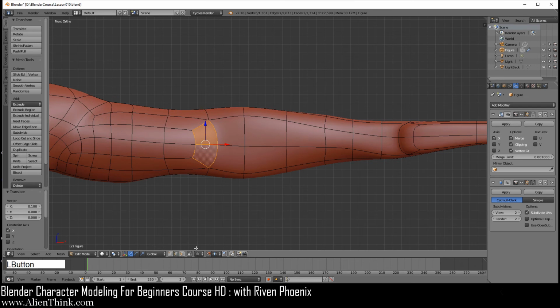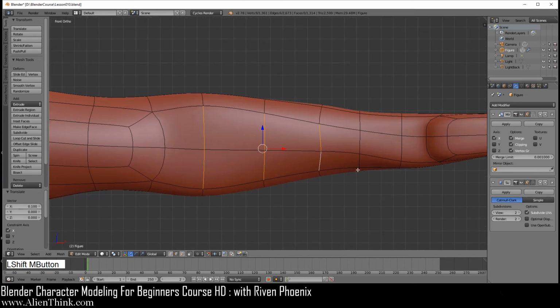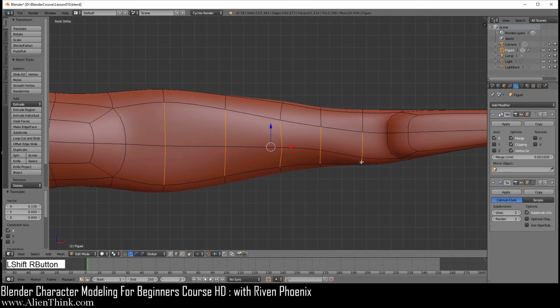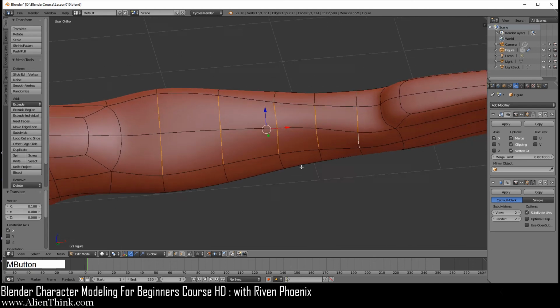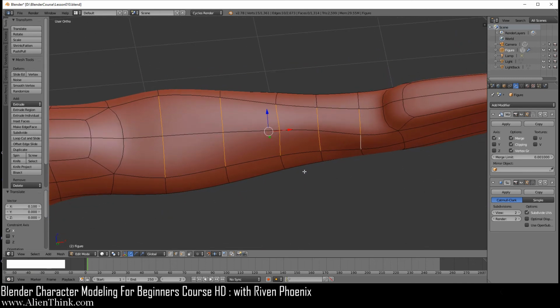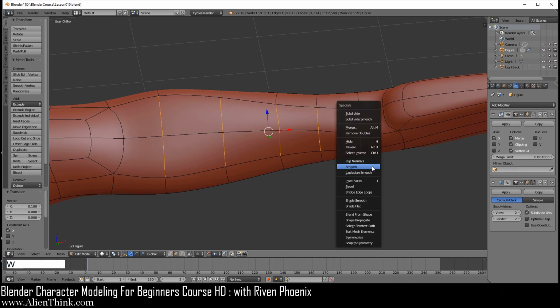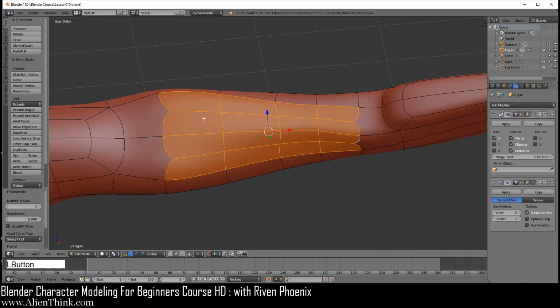Okay, go ahead and select on the edges. Now we can select on this edge, shift key down this one, this. I'm just going to zoom in over here. Select on all these edges over here. Okay, so if I do middle mouse button, you can see how we've selected these edges. Now we're going to do W and we're going to do subdivide. We've only used this feature really one time when we started out with the box to start the course in the first lesson. Now if I do W subdivide, you can see that what it does is adds all the edges going horizontally over here.